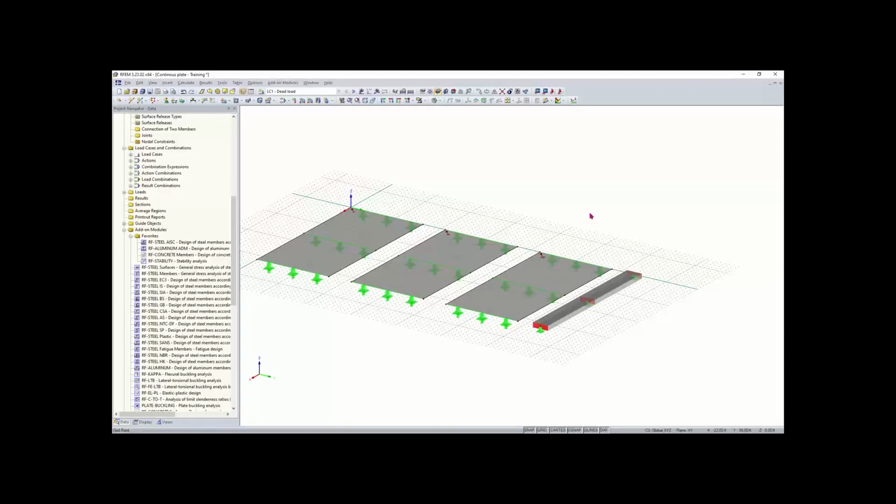So yeah, and I would just add to that, just like what Alex said, the analysis is completely within RFEM, and all materials are available to you there for full modeling for the analysis. And then, as he mentioned, the modules are for design. So within the RF concrete modules, you would find the various standards, such as the Eurocode, the ACI, the CSA standard, to actually do the reinforcement design, which is not done within RFEM. So I think that's good.